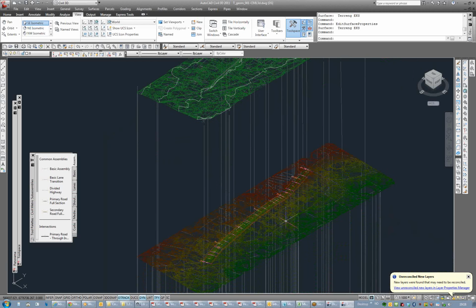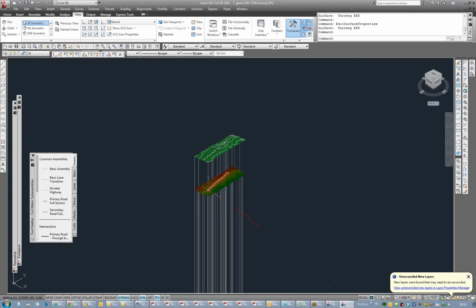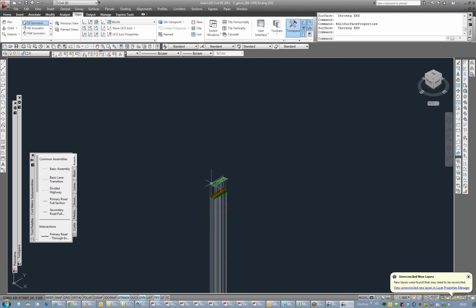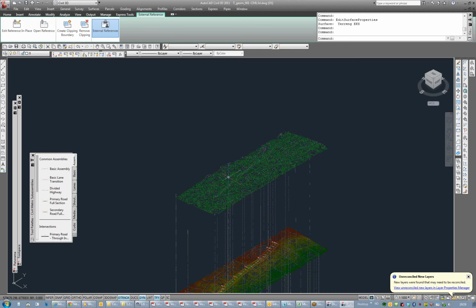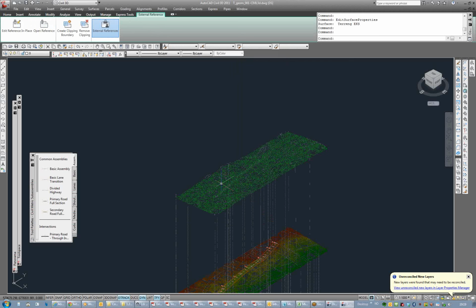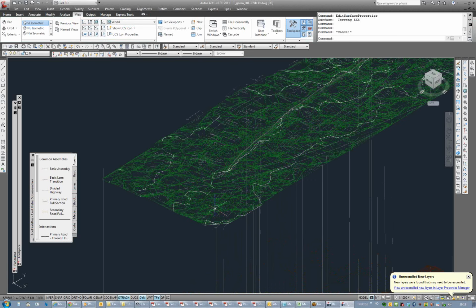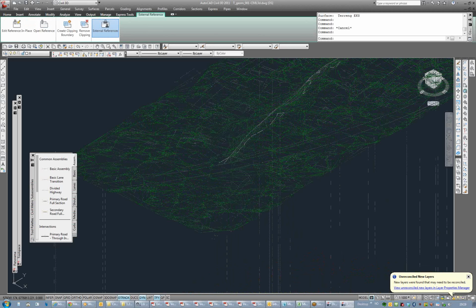And where is the survey data? That would be, go ahead and set that SOCI surface, pick it, okay. Right click, edit surface, nope, you got the extra up there. Still got the extra. Why don't I turn those off? We're going to go down to the one below that.